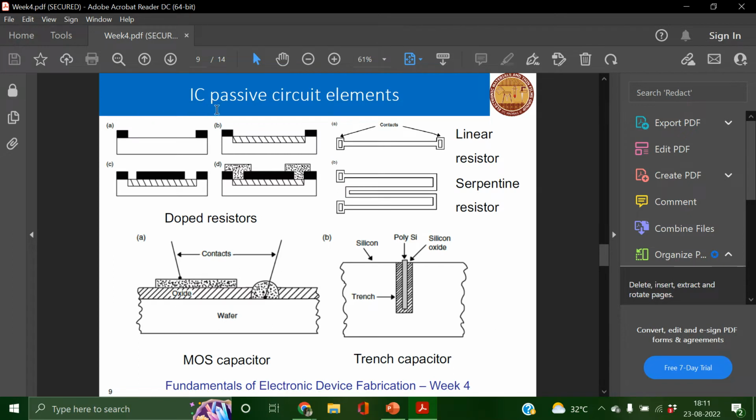And this is a highly automated system where the wafers are loaded and unloaded using isolation pods. And then we went on to see the different circuit elements. We saw both active and passive circuit elements. Passive circuit elements include resistors, capacitors, and so on. Doped and undoped regions would act as resistors, and whenever we insert a dielectric layer, that would serve as a capacitor for charging.